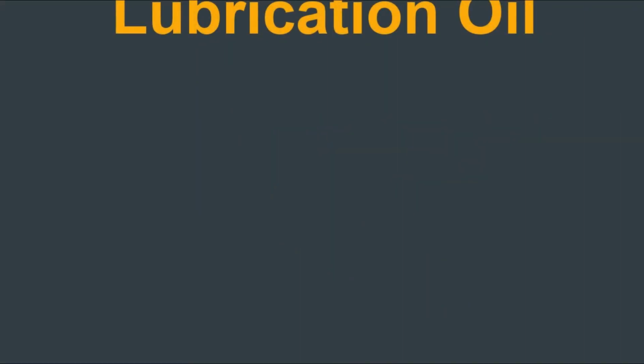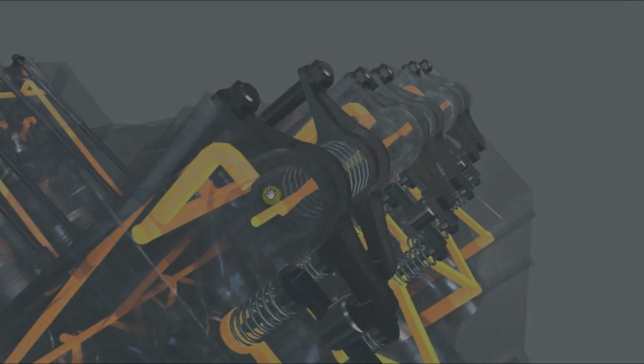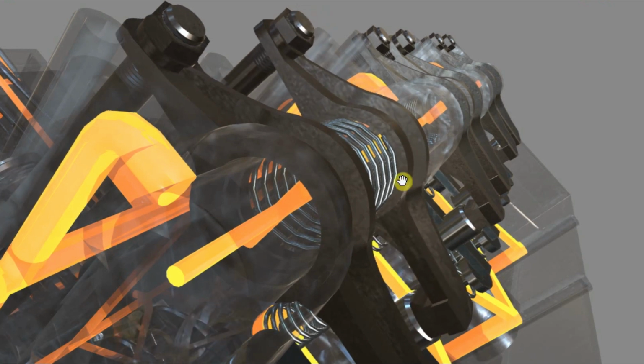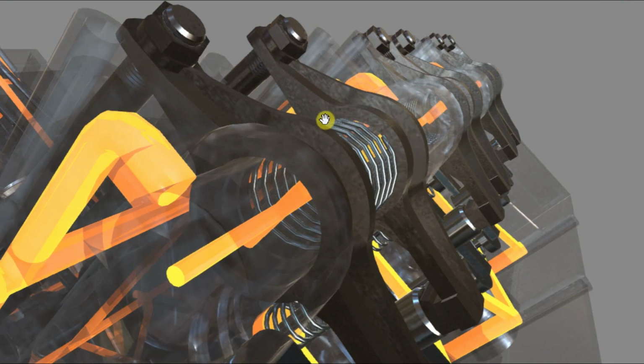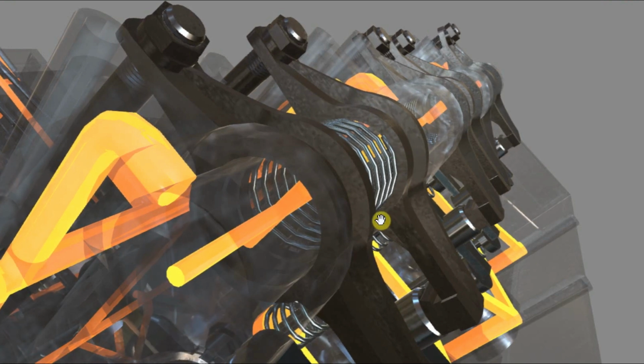We send the oil to all the areas of the engine that move. In other words, if the rocker arms are moving up and down, they're pivoting, we can see we're going to need to supply oil into this area in the rocker arm, and we're going to press the oil out all around this inside of the ring so that when they operate, let's just see that occurring, maybe we can.